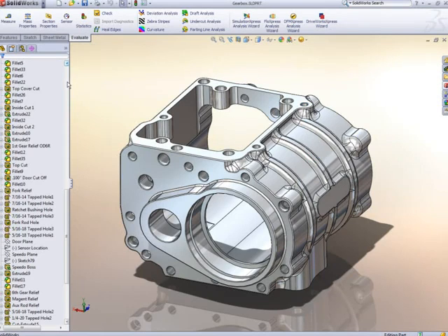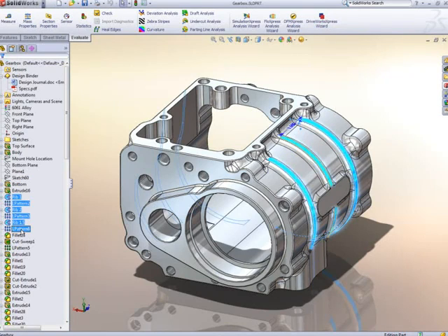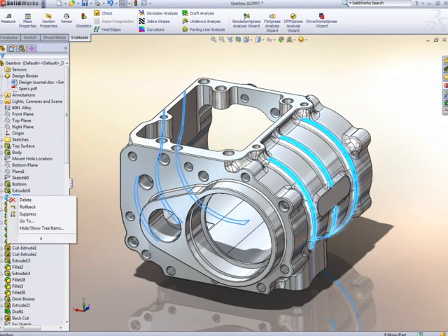Finally, let's see how information is organized in the Feature Manager. Design specs or other documents can be contained within the Solidworks file, so all relevant information is stored together. Features can be grouped into folders to make the tree easier to read, and then may be suppressed as a group as a fast way of making configurations of parts and assemblies.